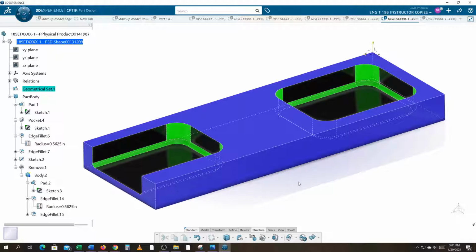If you have an opportunity to talk to your shop, talk to them about your design. They usually can tell you, hey, we can't really do that, or this would be better if you do it this way. You'll get information. You'll know how to go back and design your parts to make them more producible in the shop.